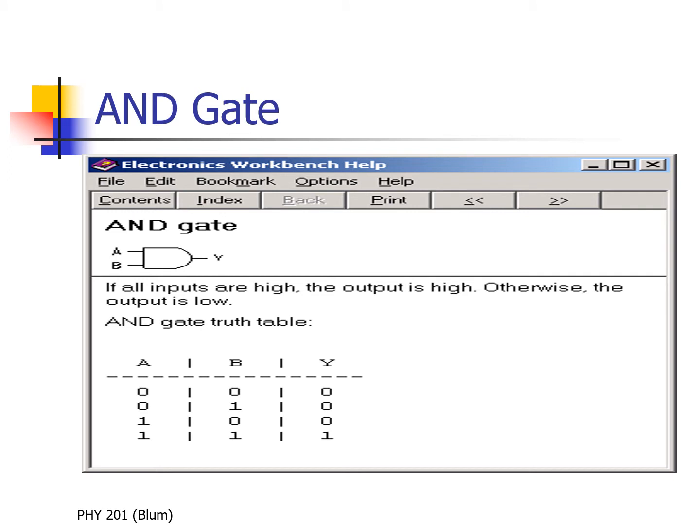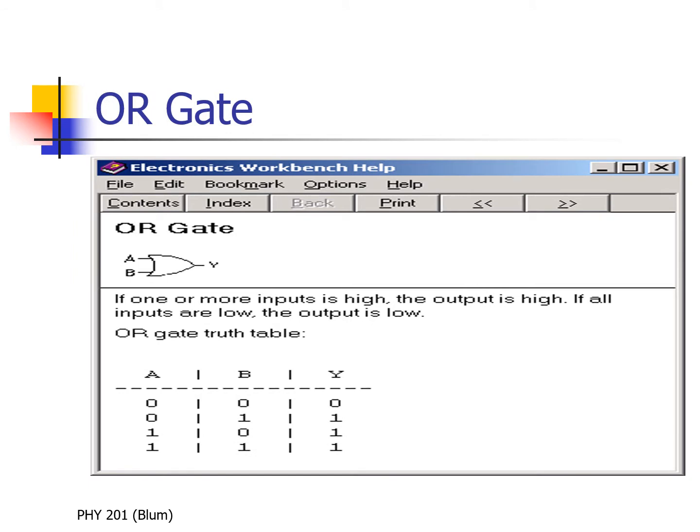A two-input AND gate takes in two binary inputs A and B, so A and B can be either 0 or 1, and it produces an output Y. Y is only 1 when both A and B are 1s for an AND gate. A two-input OR gate takes in two binary inputs A and B, and it produces an output of 0 only when A and B are 0s.